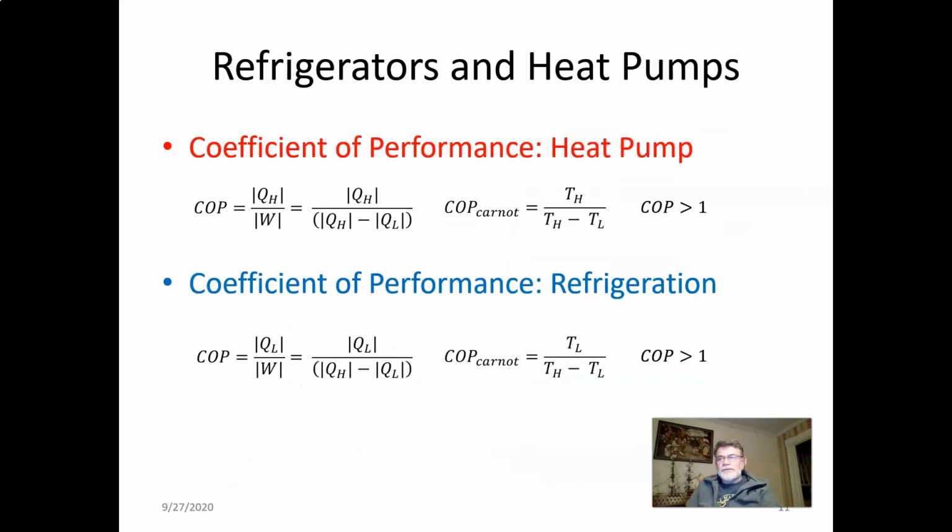So a little bit more on the COP, the coefficient of performance. The COP of a refrigerator, air conditioning system, or heat pump is the ratio of useful heating or cooling provided to work required. So higher COPs equate to lower operating cost. The higher it is, the better it is.